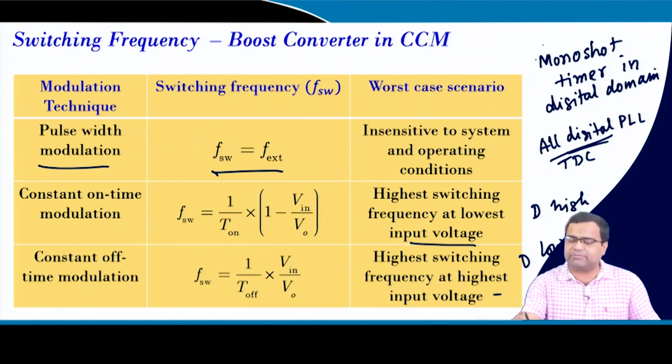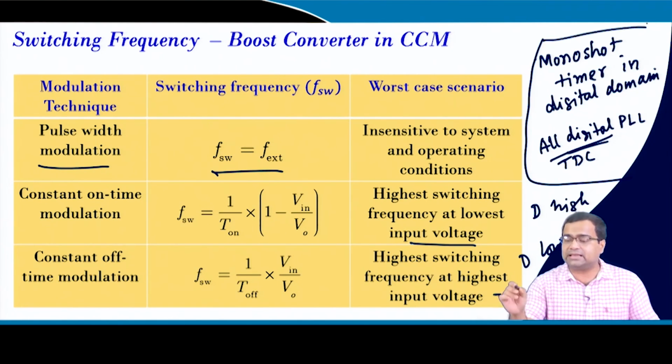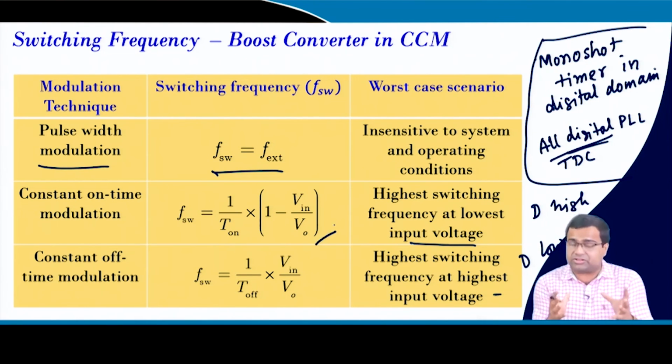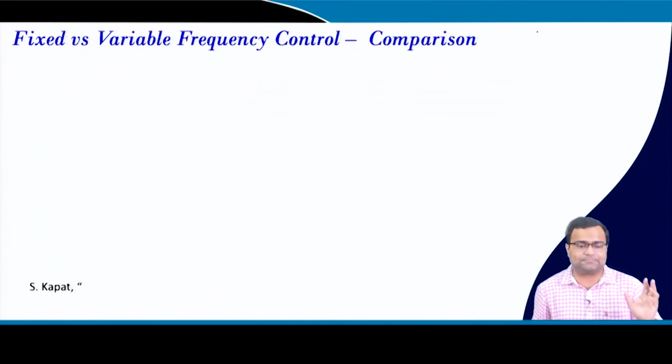And in digital implementation, these are very easy, and that is why the constant on off time controls are coming with digital assistance, even though they are implemented in analog in the majority of commercial products. But for the timer adaptation we can use a digital technique, and then you can solve this variable frequency problem, and you can get the benefit of the best of their features.